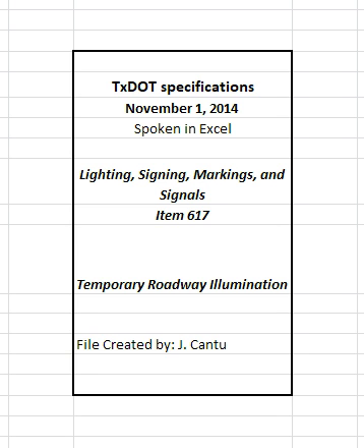Operate and maintain the temporary illumination system. Relocate temporary illumination system as shown on the plans. Remove temporary illumination system when no longer needed. Remove abandoned concrete foundations to a point 2 feet below final grade. Backfill the hole with material equal in composition and density to the surrounding area. Replace surfacing material with similar material to an equivalent condition.